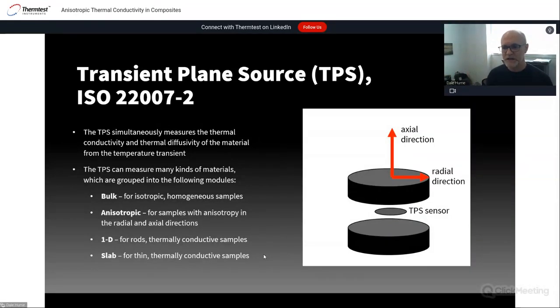And if you have anisotropy, the assumptions for the anisotropic measurement are that the anisotropy is well organized. So that is a condition either of a filler that's well dispersed and aligning in one direction versus the other, or if it's a layered structure that they are repeating. That's really key. If it's not well defined, the more disorganized it is, the more potential there is for error. You'll get two directions, but that will influence the accuracy of each direction.